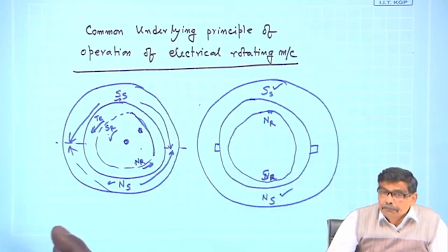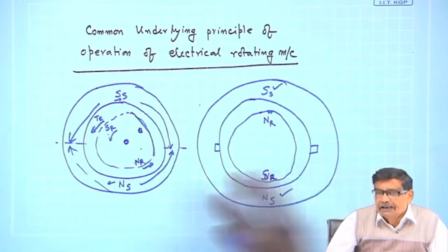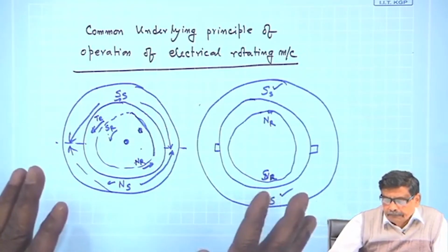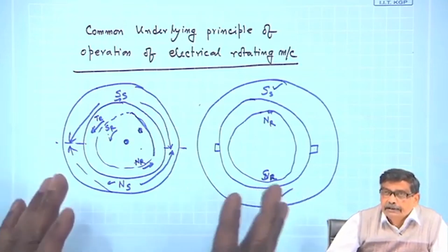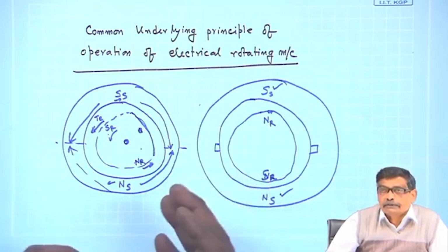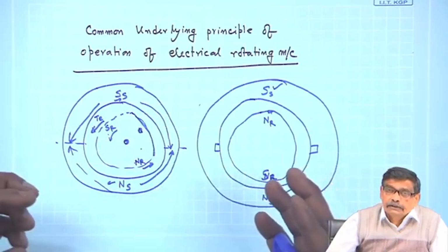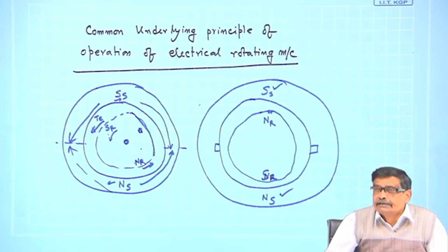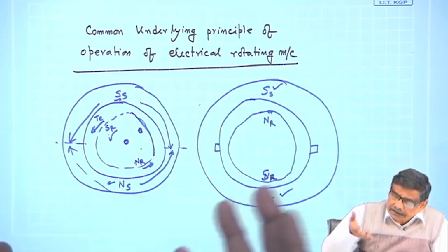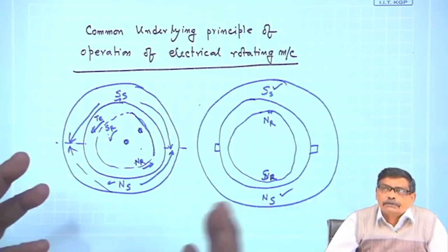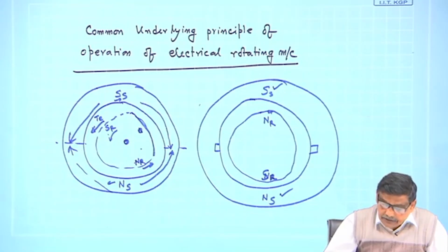But the important point is, we will see later that even stationary coils will carry some current and still can produce poles which will be found rotating. That is a great achievement, and it was first pronounced by Nikola Tesla. That is, even a stationary coil can produce a rotating magnetic field. So, let the rotor move, that rotating stator field will also move, such that the angle between these two will remain constant and give you sustained torque.